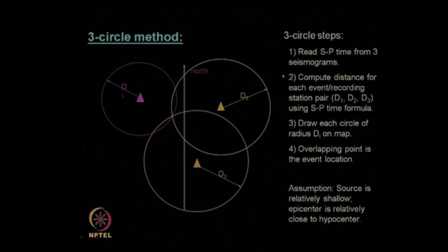That means, all over the world you have to select a minimum of 3 seismograph stations where reliable data has been recorded for both P wave as well as S wave, and get the time difference of arrival of the P and S waves from those 3 minimum seismogram stations.